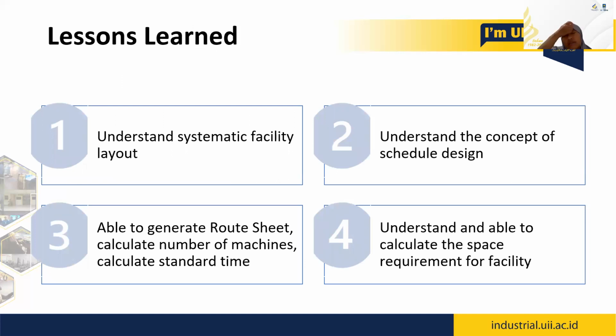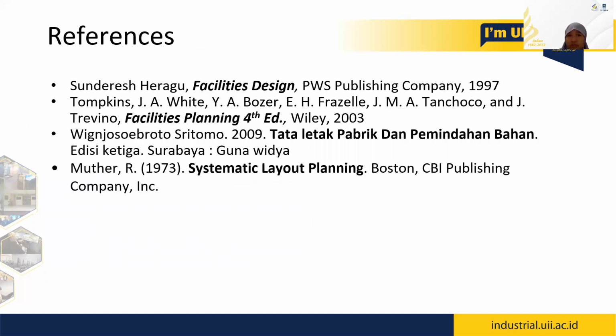Okay, so today we have reviewed again the systematic facility layout and the steps on how to do that, by understanding the concept of schedule design and by being able to generate the route sheet, calculating the number of machines and standard time, so that we can find out the space requirement for the facility.